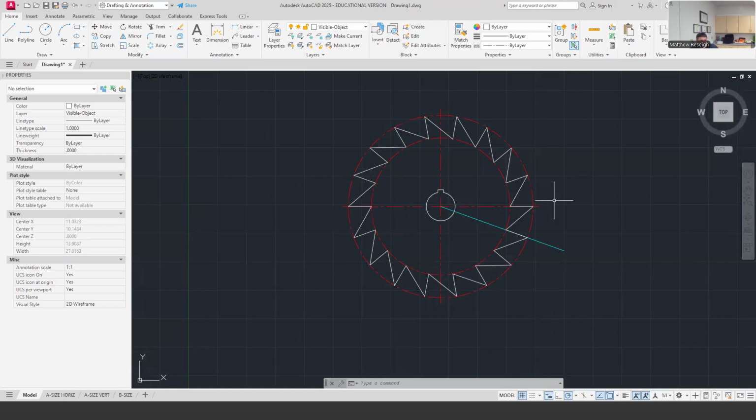So if this is cut out of 1/8" plate, maybe it's an 1/8" metal part. A company that's thinking 5S, Six Sigma, or lean manufacturing concepts will, as jobs come in, grab all the parts that are 1/8" thick. They bundle them together on a sheet and organize them to maximize sheet cuts. I'm not going to grab this part, put it right in the middle of a 4x8 sheet, and cut it. I'm going to nest. Somebody's job is usually to nest all these parts